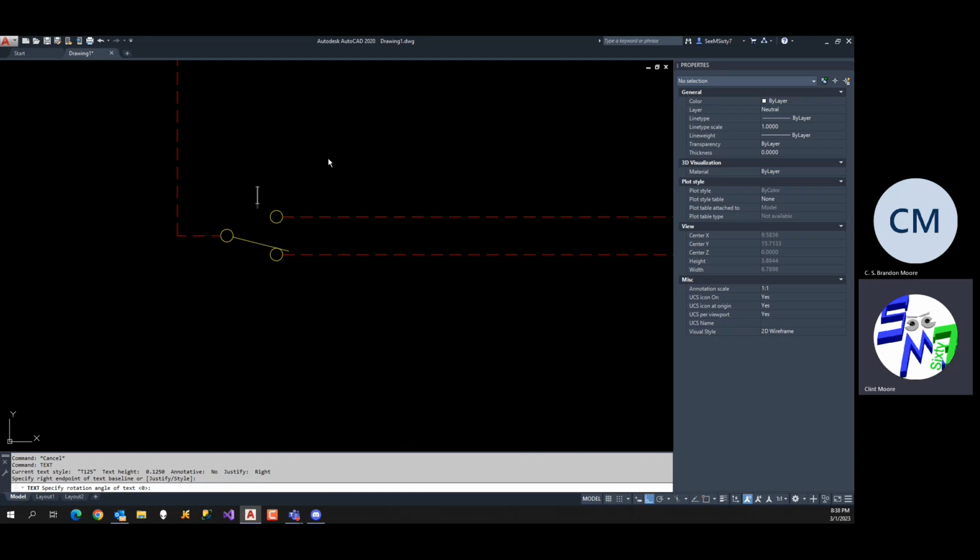For legibility, you typically want your text direction to be between 0 and 90 degrees. You want to avoid going 180 or 270 degrees. You don't want to have upside down text. You read the way the prints are printed, so you want it to go 0 or 90 degrees. You want to stay in those orientations. When I'm typing at this interface, it's going to draw it across the screen where it's legible, so I can read it easily. But when I finish, it's going to rotate it up.